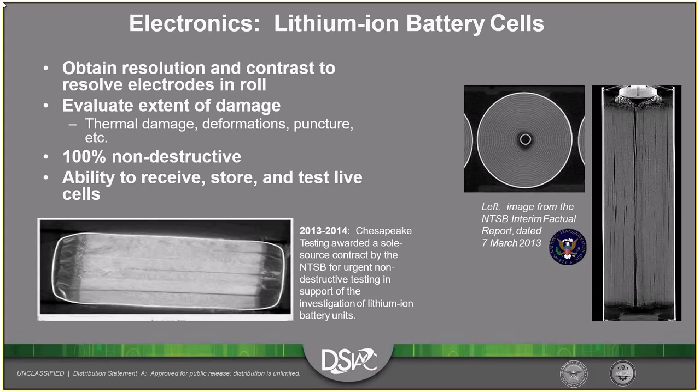You can actually go in and measure tab welds, rupture disc thicknesses, CID devices. Everything inside, the CT scan you can measure and quantify and actually trace back to specific manufacturers, which is very helpful on the failure side of things and also upfront, making sure you have what was advertised to you.